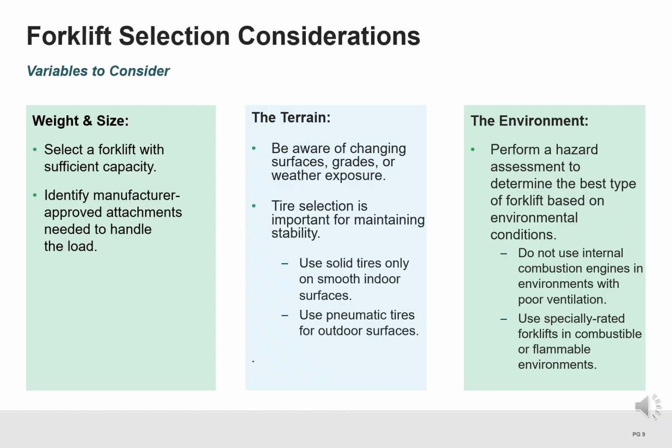Finally, consider the environment. A hazard assessment should be completed to determine the appropriate equipment. Do not use internal combustion forklifts in poorly ventilated areas, and use specially rated equipment in combustible or flammable environments. Selecting the right equipment is critical to safe operation.